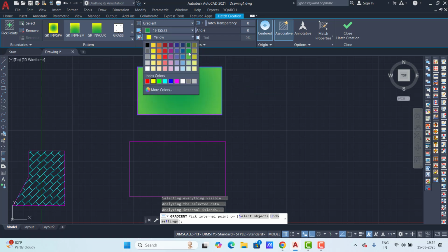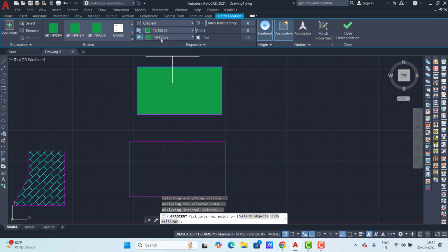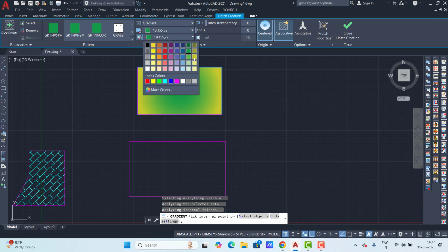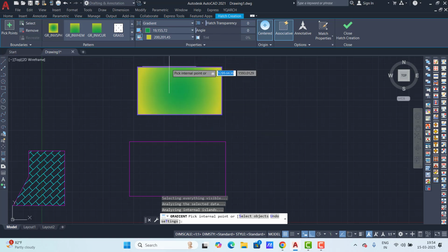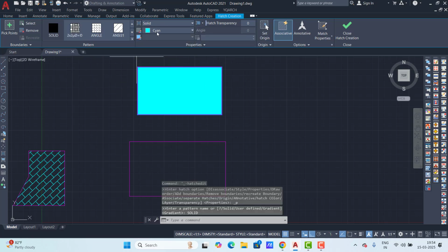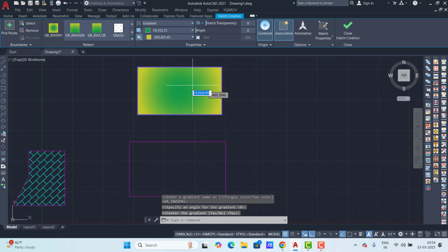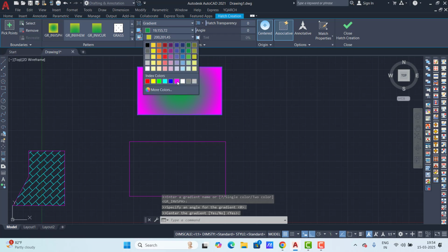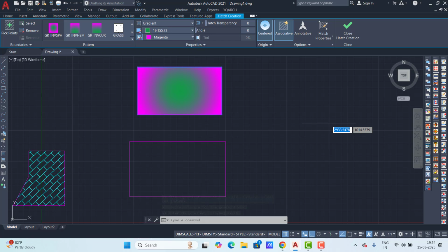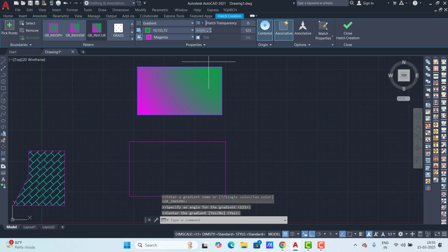Similarly, if you want polyline form, BO, enter, select polyline and pick points. First, second, third, and close, and enter. Just move. Select and drag here. If I want to select the object downside this line but an overlap comes, just select this line and we can reverse it. That option I have; I will explain it next day. Bring to front, send to back. Now we can select the polyline form only.